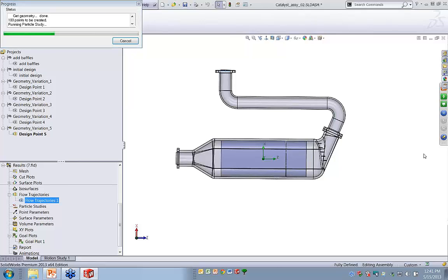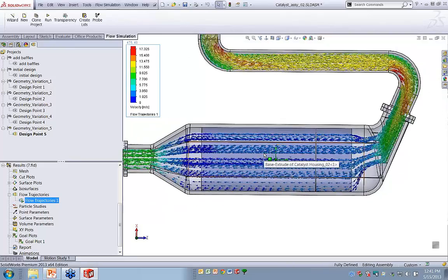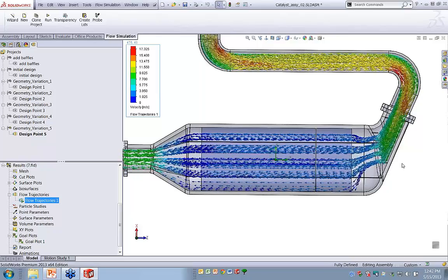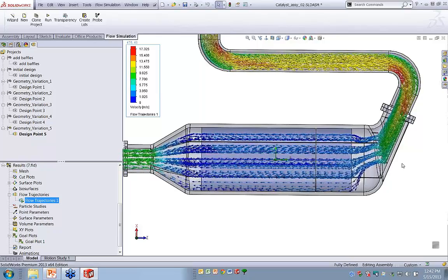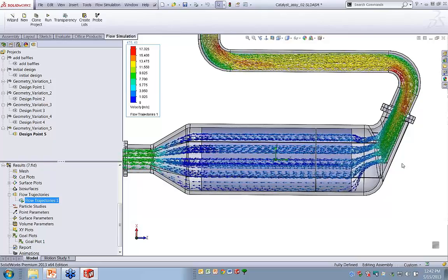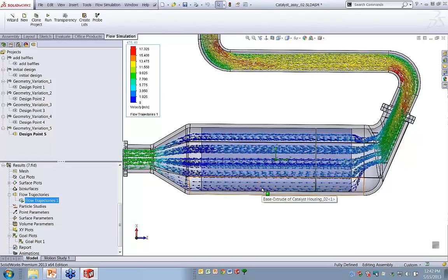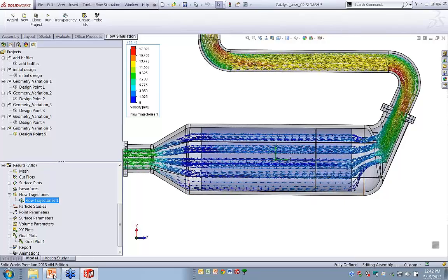And we'll be able to see right off the bat a huge difference, right? Compared to the previous flow trajectory we saw, where everything was so heavily based on the bottom, now we can see that it's much more even passing through the catalytic converter. What does that really equate to in real terms? Well, that equates to actually having a longer lifespan, right? This is a better product. And we use flow simulation to basically target that perfect angle for this type of analysis.